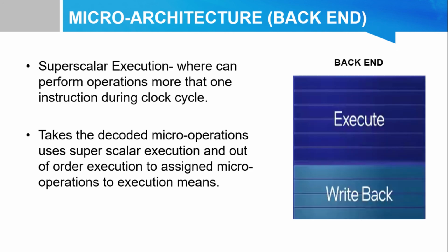The back end has execute and write back, and has superscalar execution, which can perform operations of more than one instruction during a clock cycle. It takes the decoded micro-operations, uses superscalar execution and out-of-order execution to assign micro-operations to execute means.